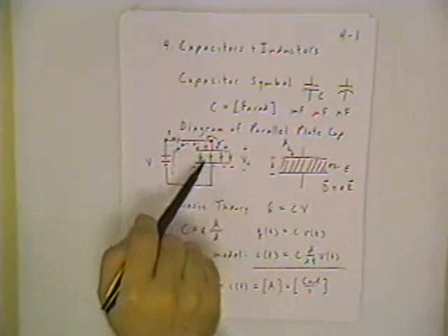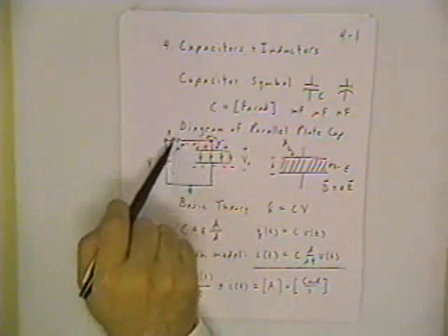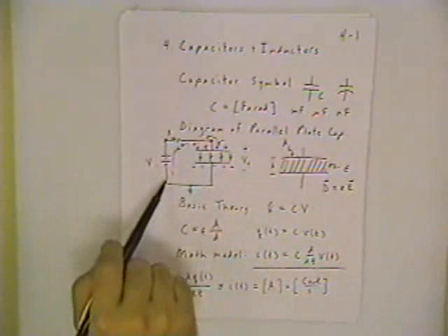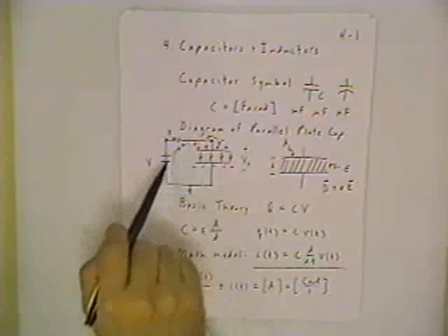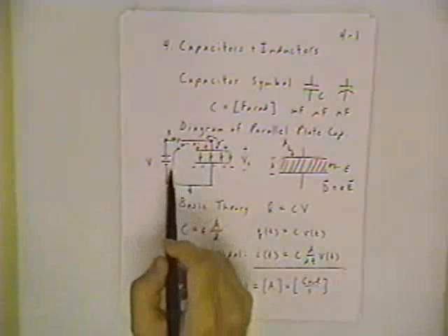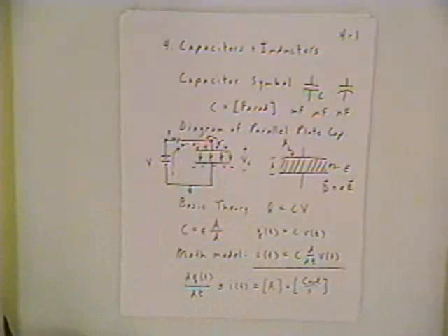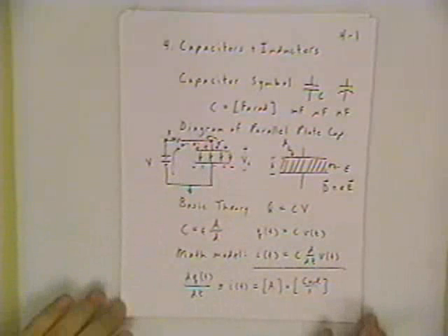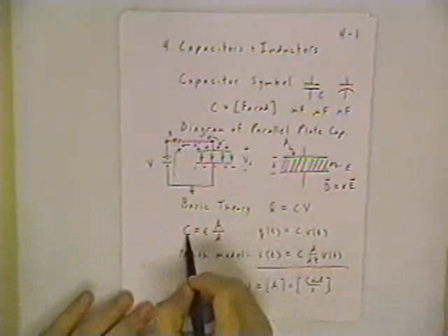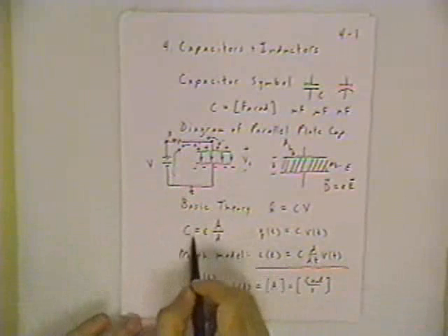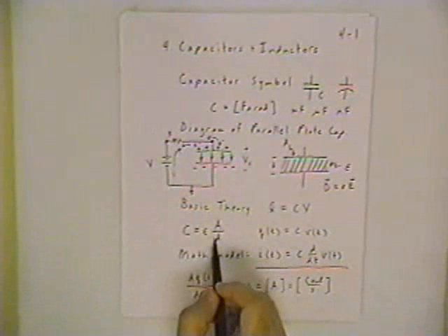Until that fully charged condition happens, you still have current in the resistor, and that means that there are some expressions we can come up with for calculating the current as a function of time. And we'll get to that in turn. Keep this basic model in mind as we talk about capacitors in series and parallel and equivalent capacitances. That'll help you understand where these come from.